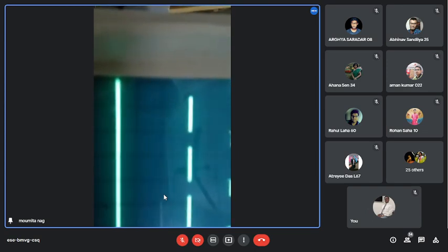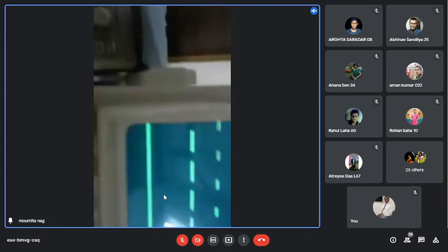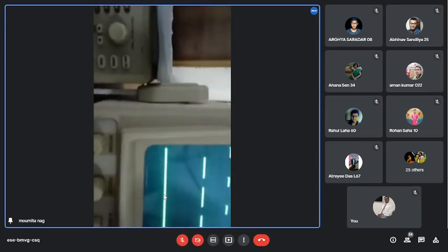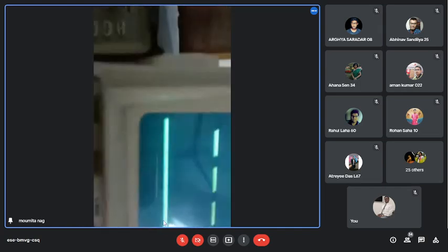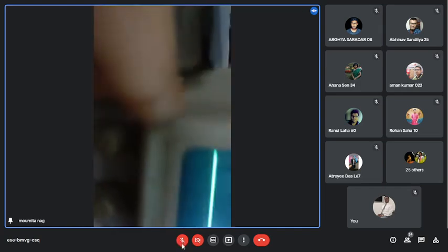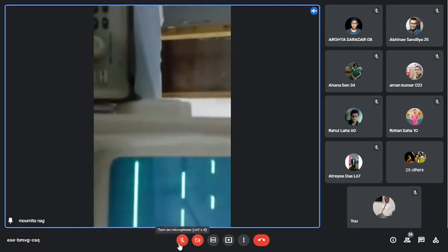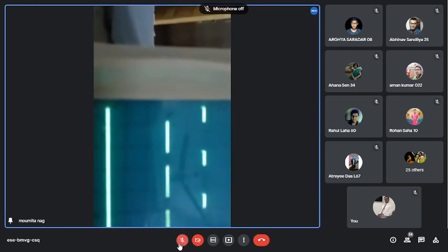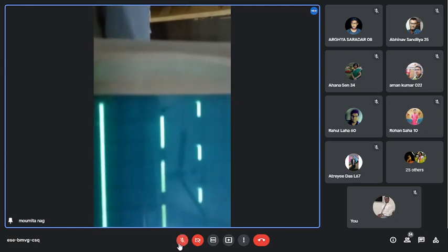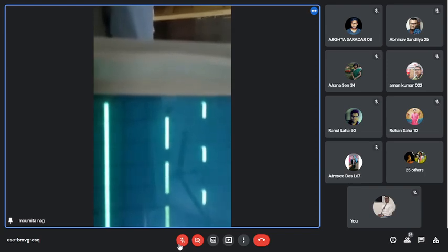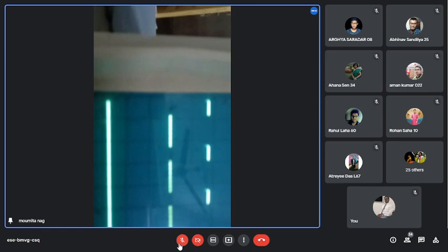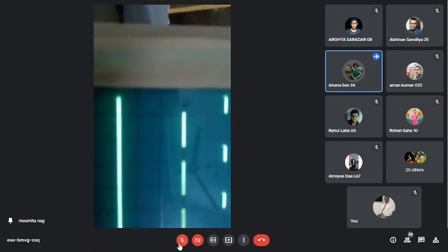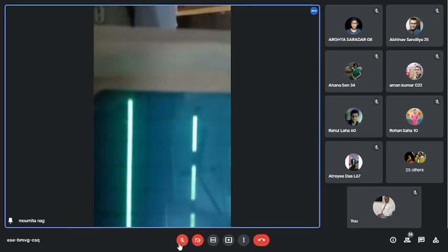Okay, note down this. And what is the T off period? There are one big division and two small divisions. That means 7 small divisions are there for the T off period. So 0.7 millisecond.